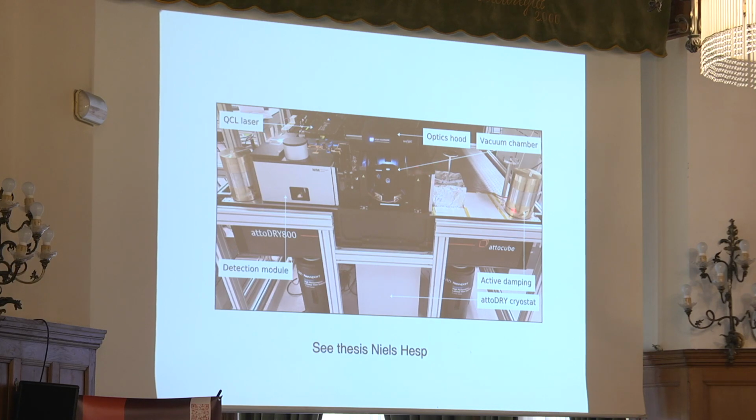One of them is actually active damping. So our system is not in a basement, so we do suffer from building vibrations. And Niels came up with this active damping, which is basically big pieces of metal, very heavy. And on the bottom there's a piezo, and then we have an accelerometer sitting on the ground somewhere, and then with active feedback it is actually compensating the vibrations. Exactly, it's 16 hertz, which is the eigenfrequency of this cryo SNOM. So that helped a lot.